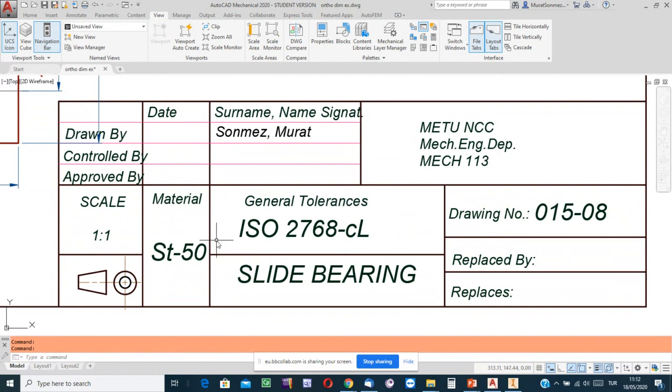In this course, you're responsible for the associated things on size tolerances, where the lowercase letter in this example stands to say the tolerance class is f. This week I'm going to clarify what tolerance class means. So for non-functional dimensions, this address is the correct place to refer to at the beginning, and then see the tolerance class letter and deal with the rest. Refer to the correct table and determine the upper and lower limits.